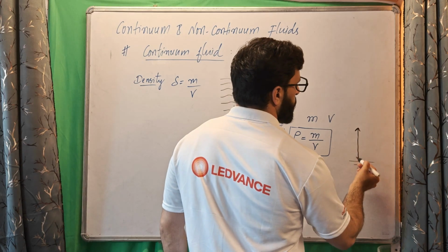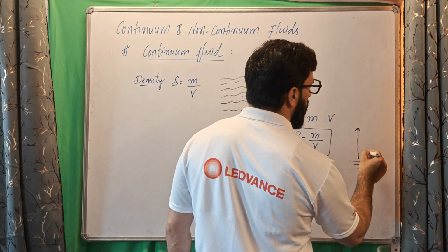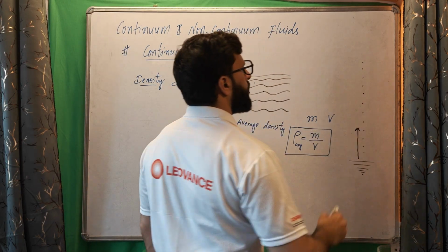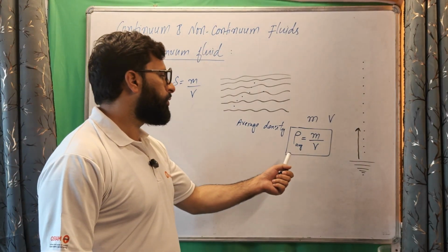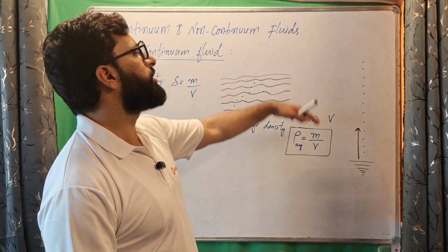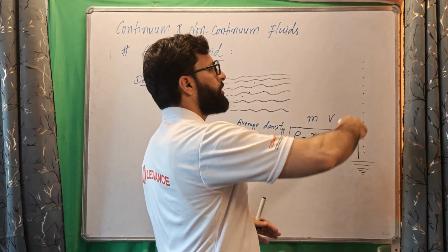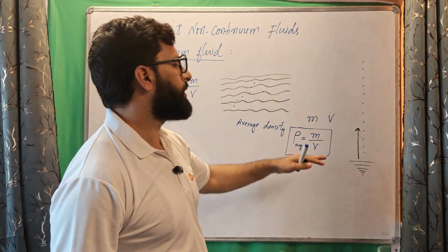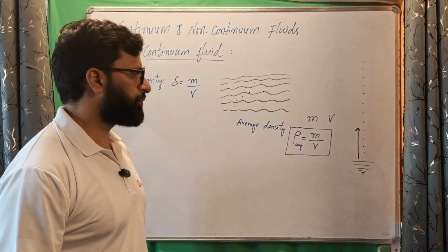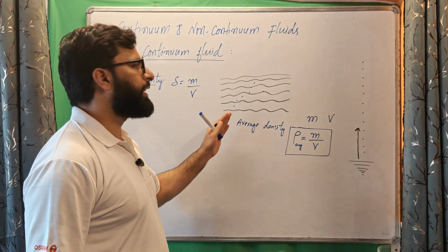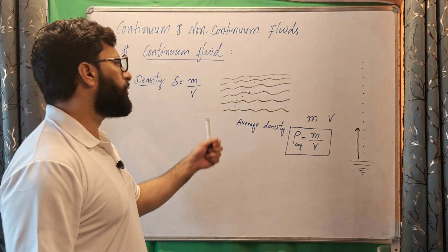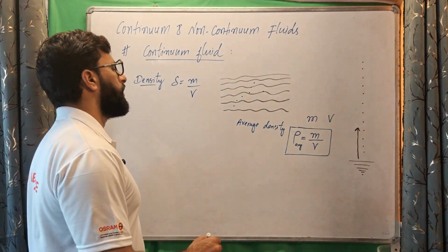As we go up, density decreases, and we want to know how density varies from one point to another in the vertical direction. We cannot use an average density for air, saying the average density of the entire air, or of the air from this height up to this height, is this much. We are interested in knowing how density varies as we go up. So we want to know how density varies inside a fluid. This is the important question. So we have to come out of this average, and find the actual density value at a point. Now let us find that.